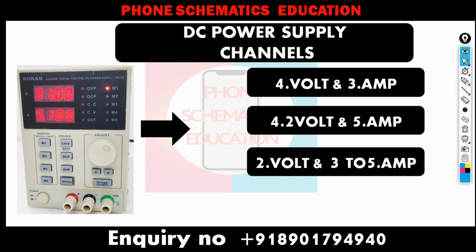Right, now next, 2 volt 3 to 5 amp. First using 3 amp, then 4, then 5. This one I'm using for the many lines that have 1.8 volt or 2 volt shorting in the secondary lines.